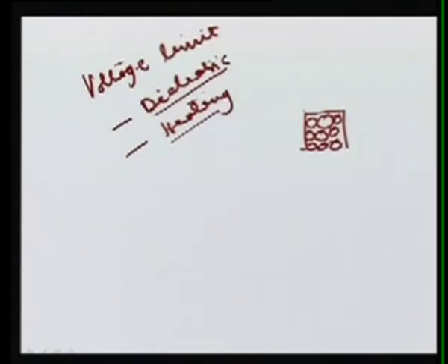So what happens at these corners, we have the excessive field and therefore more eddy current flowing in this core. This is basically your rotor and stator as well. So there is more eddy current and more loss. So if you are going for more voltage, more flux and more stress will be there, and there may be heating, and that is not desirable. So the maximum continuous limit due to the excess flux is lower than the breakdown consideration. Therefore, the limit due to the excess flux is the determining limit.